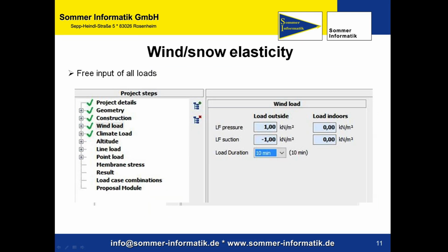With regard to wind and snow loads, it always depends on the country which wind and snow loads and which norm are applied. Here you have the option of manually entering all loads in a relatively neutral wind and snow load module. Here we would also like to point out that we can enter the load duration for wind load once for 10 minutes and once for correspondingly lower values in order to be able to consider the country-specific variations.